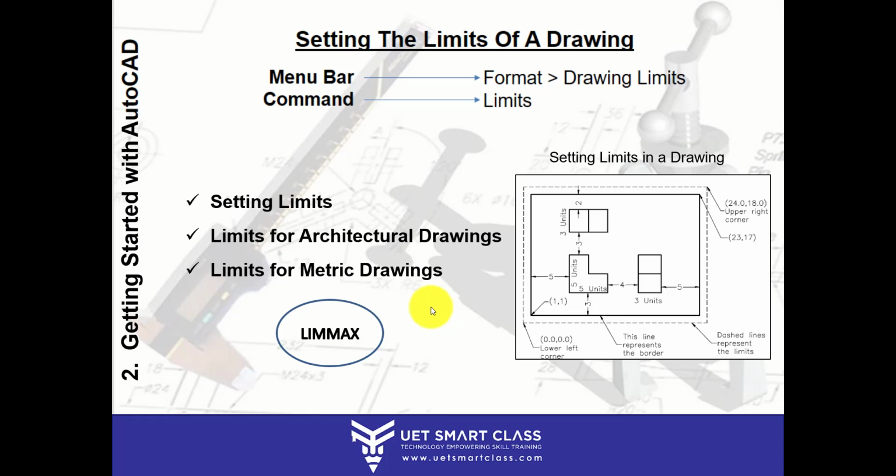So if you're setting, like the example I gave, 10 by 10, your x limit will be 20 into 10 and y limit also 20 into 10. But those units are in meters. When you're working in metric drawings, you have to convert them into mm. So you also have to multiply both the x and y values by 25.4. So that will be 200 into 25.4 and 200 into 25.4. That comes to 5080 for both the limits.